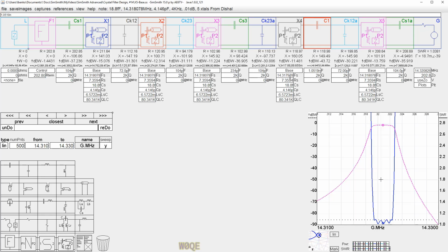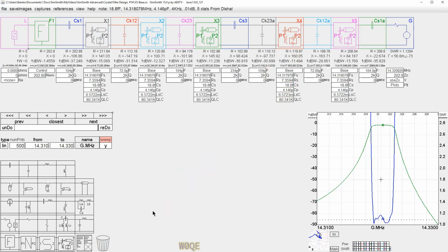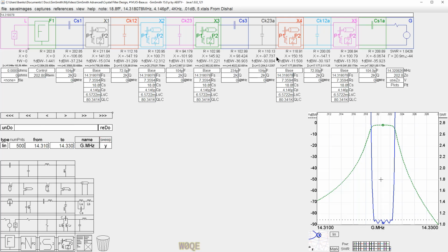So these do not have to be matched super accurately. So we say get these matched within 100 hertz, maybe get them matched within 50 hertz. Here's where I don't want to be giving advice on what to do, because everyone's tolerance for how they do things is slightly different. What I'm saying primarily is, if you want this to be as good as possible, there are things you can do that make the job easier. And starting with these two crystals being the same frequency means you don't have to worry about any capacitance in series with them. They're both the same.